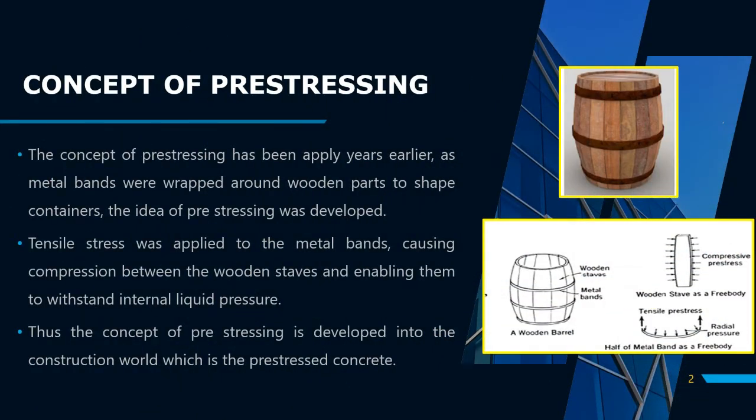My name is HUSAINI bin ROSLI, and I will present about the concept of prestressing and the principle of prestressing. Concept of prestressing. The concept of prestressing has been applied years earlier, as metal bands were wrapped around wooden parts to shape containers. The idea of prestressing was developed. Tensile stress was applied to the metal bands, causing compression between the wooden staves and enabling them to withstand internal liquid pressure. Thus, the concept of prestressing is developed into the construction world, which is the prestressed concrete.